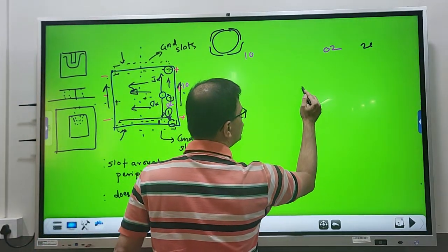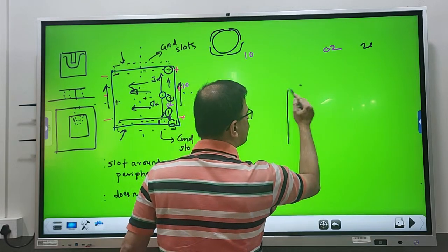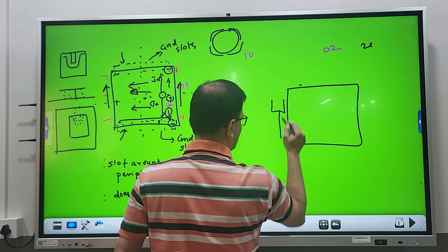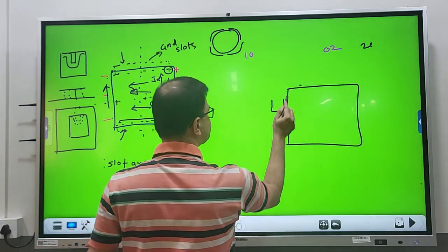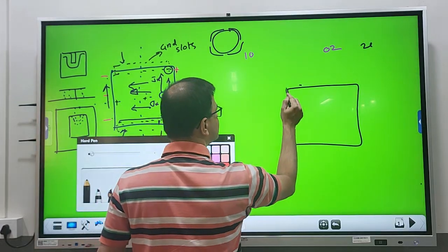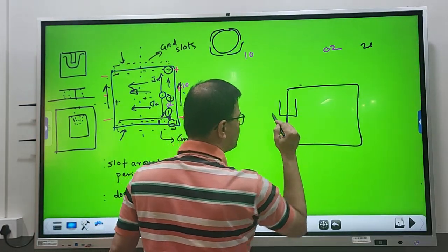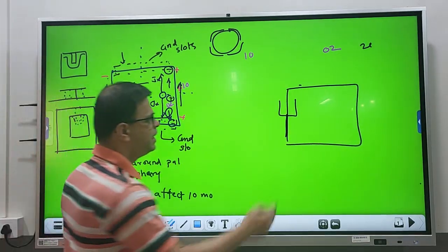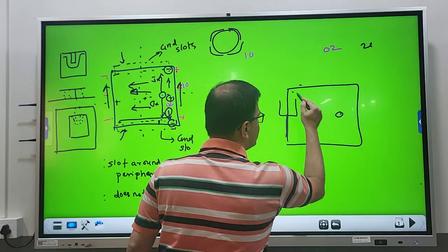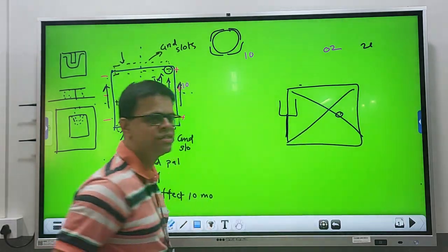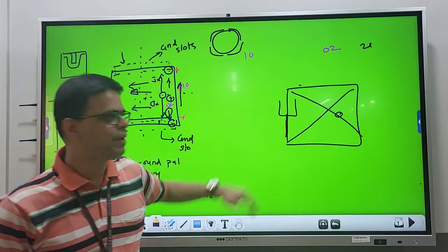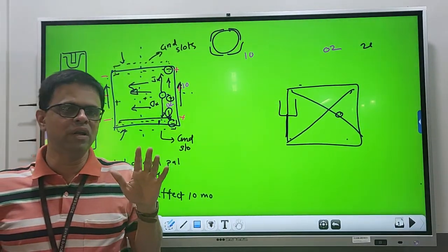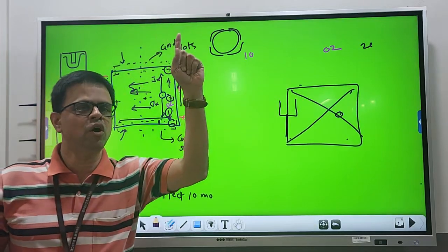So here what you can do is, when you have a radiating patch and you create this slot below the patch, I should say, not over here. This is the slot below the patch. A similar effect it does. This is the feed point location, and it creates two diagonal modes. Because when you have a slot like this below the patch, definitely the diagonal distances are different along the two diagonal lengths below the patch, and that has an effect on the radiating patch.